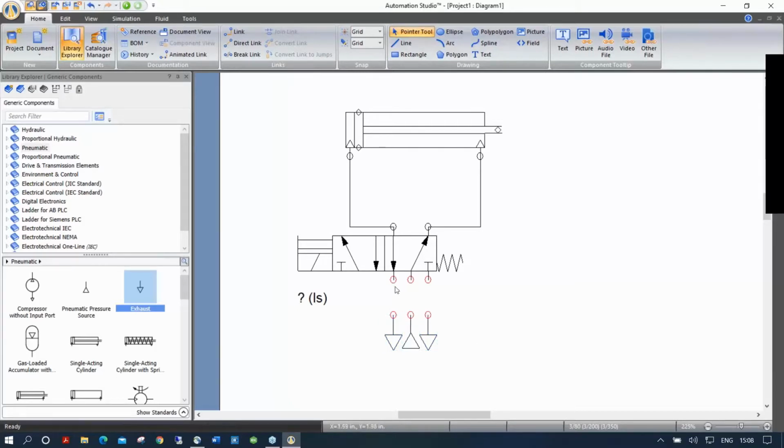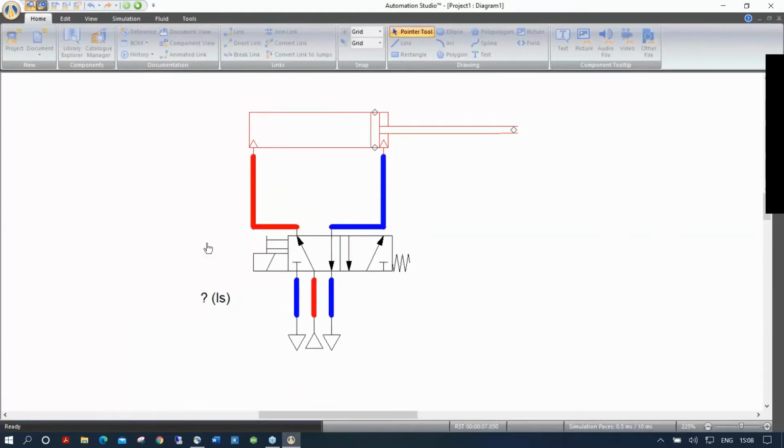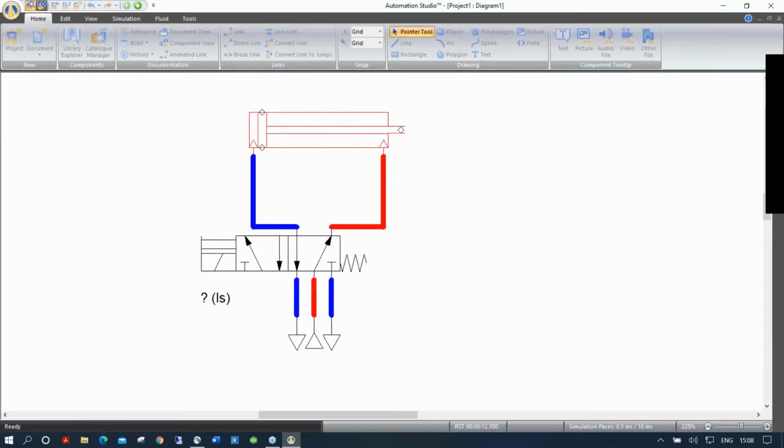Okay? So make the link here, copy here, click here, click, click, click, click, and click. So now that I have created this circuit, I can directly go into the simulation mode and actually push on that button here to test my circuit. Every time I let go of the button, it brings back the valve because of the spring on the other side. Okay? So you may feel like it's moving a bit too quick, and you want to slow it down a bit for the students to have more time to see what's going on.